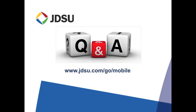Thanks. And to go along with that, another question we had come in is what kind of interference is analyzed by the JDSU test unit? Generally, it comes down to spectrum analysis, looking at different ways of presenting spectrum data, whether through a timeline or through a spectrogram. But the other key points of using the JDSU equipment and any spectrum analyzer for that matter is understanding how to get the most from it by understanding resolution bandwidth, your spans, the type of antenna that you're using to try to increase that dynamic range, and the DANL, the noise level of the spectrum analyzer itself.